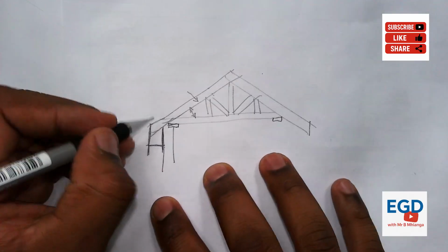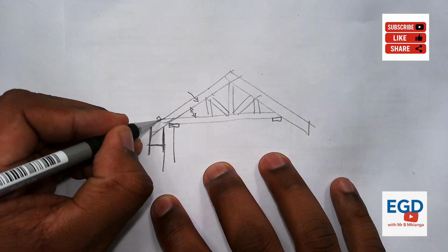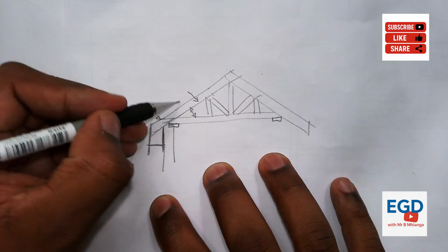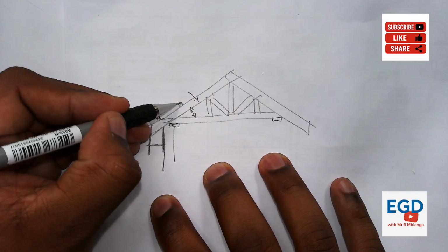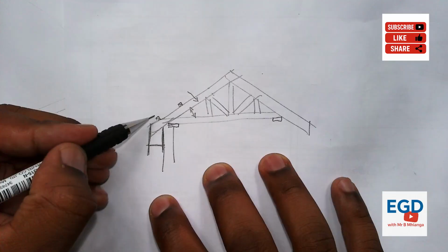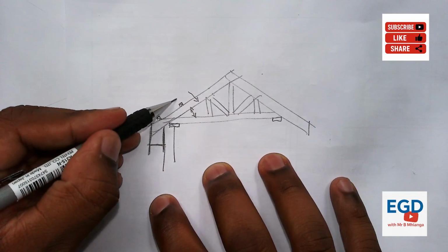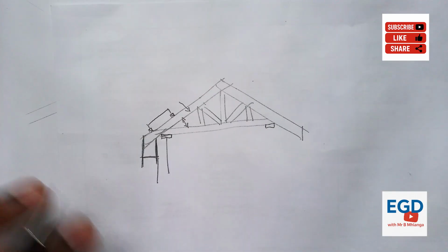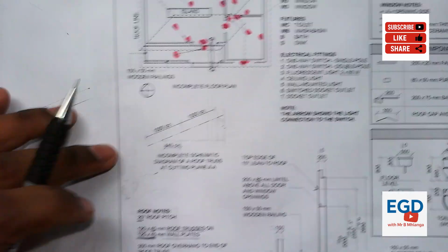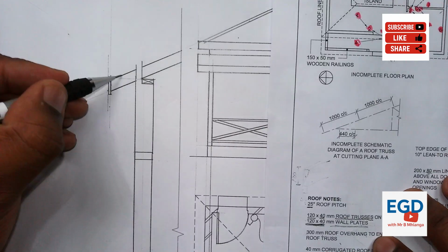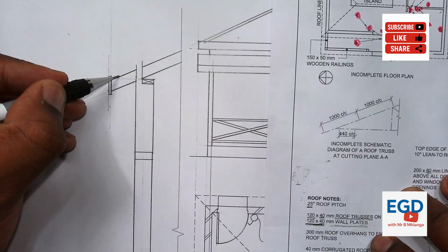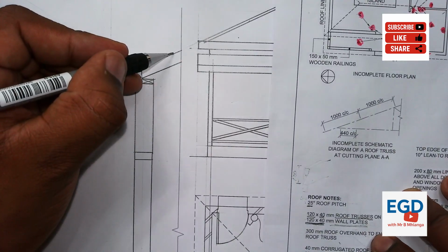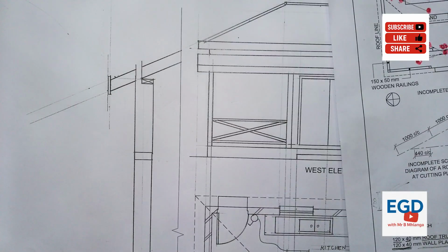It means obviously the purlins are placed on top of the roof trusses. So if I have the first one there, the next one will be placed at a distance of 1000, but from the center to the center of the next one. That's what it means. C/C stands for center to center. So when I draw in the first purlin, from the center of the first one to the center of the next one will be 1000. They're placed at a spacing of 1000.